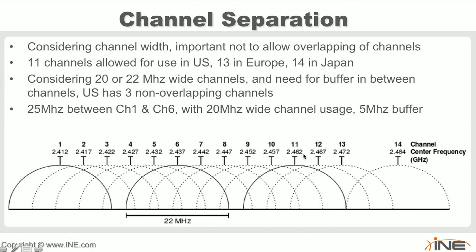Likewise, channel 11 isn't where the frequency range stops. It's not where the electromagnetic spectrum stops. I'm actually using 2452, 2462 is the center, up to 2472. So I'm actually using into channel 13. It's just that we don't use channel 12 or 13 in the US for a center channel. In Europe, the specification calls for them to be able to use up to channel 13.